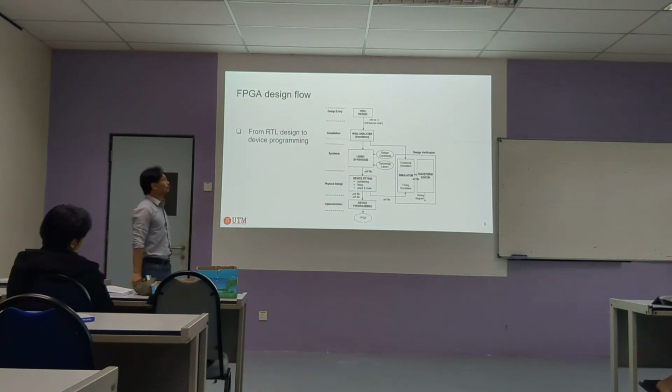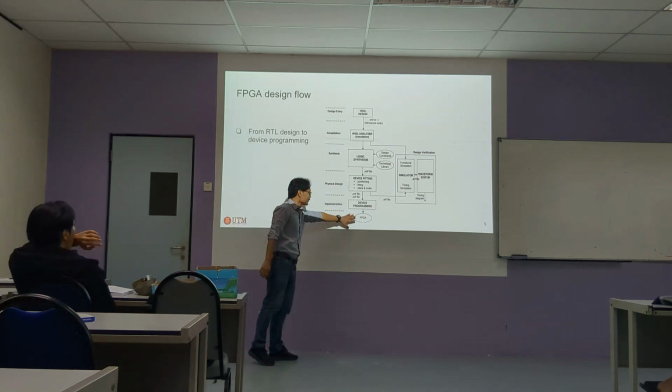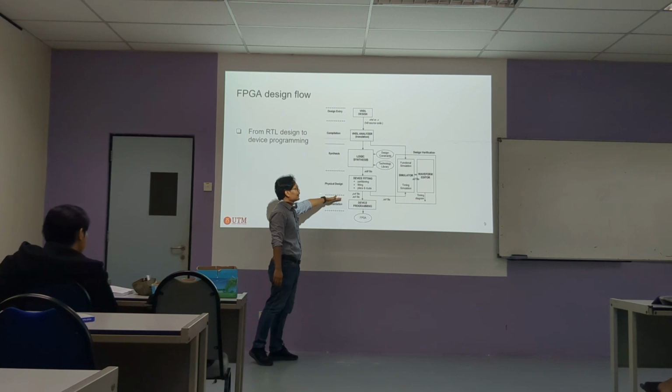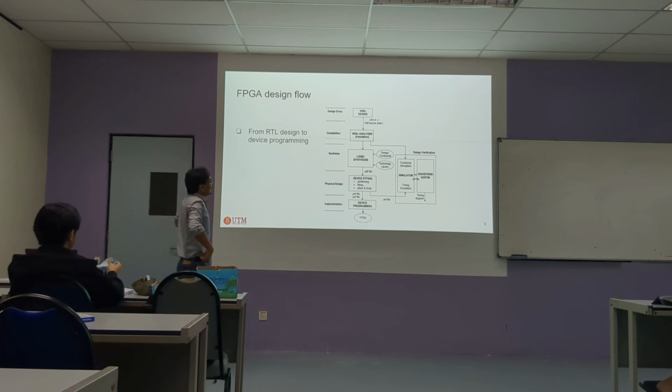And then when you talk about FPGA, basically, you can say almost the same flow. It has its own front-end design, back-end design, but now the objective is not for tape-out. So for FPGA design, in the end, you want to program your FPGA, right? You want to generate the bit stream of your design, and then the bit stream will program the FPGA. Okay, so make sure you know the difference between these two.